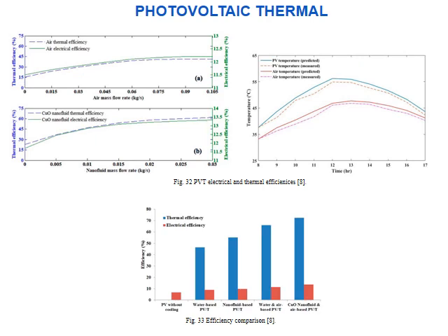Now here, let me show you the improvement that occurs when we use solar thermal. Here, let's assume we have air cooling or nanofluid cooling. By the way, we must ask, what is nanofluid? Nanoparticles, nano small particles, very thin particles, and nano, talking about nano, not micro. When we add them to water, we create what we call nanofluid. What is the benefit of this? It is to enhance the thermal conductivity of these fluids.